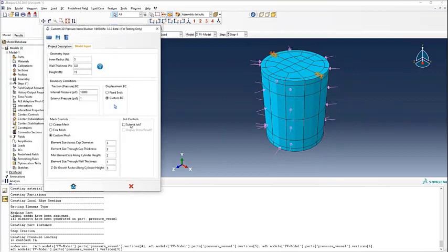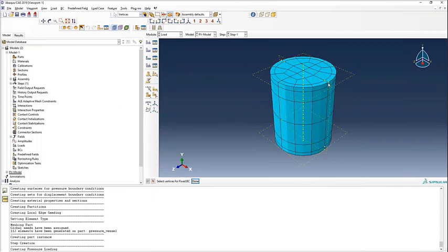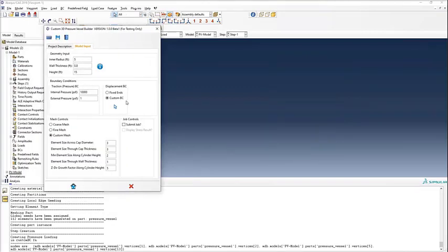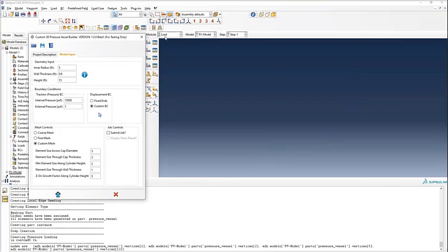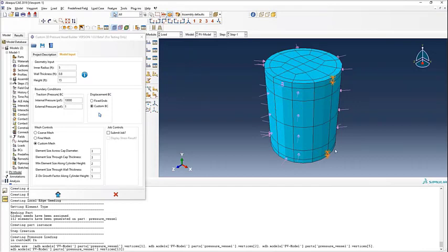If we aren't happy with that, we can obviously go and change that again. We select our pick button, it processes, creates the model. We go through and select some additional edges. Let's say it's on the side and welded to something. And again, once we hit done, everything gets sent to the kernel and it creates those boundary conditions for us. And sure enough, those vertices have been replaced with ones on the side edge.